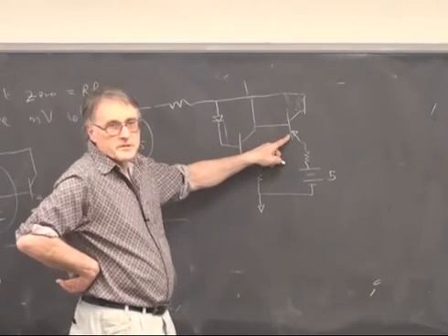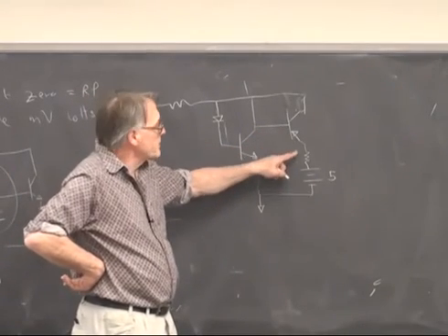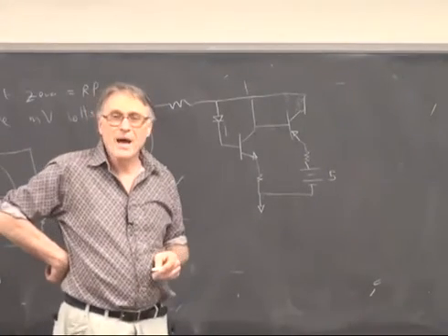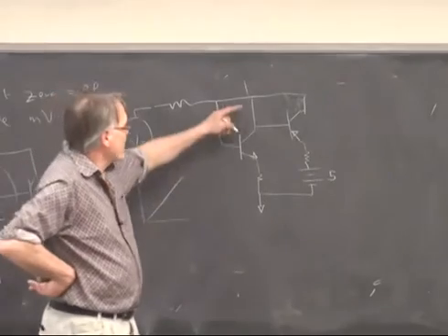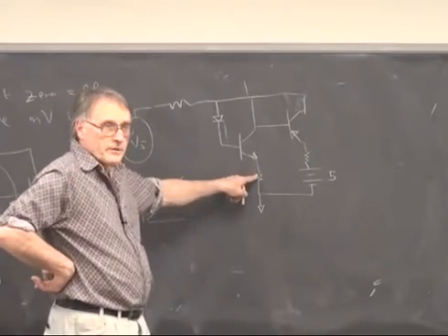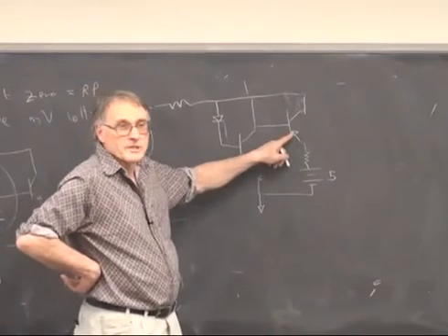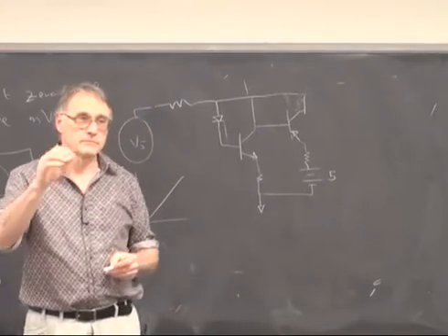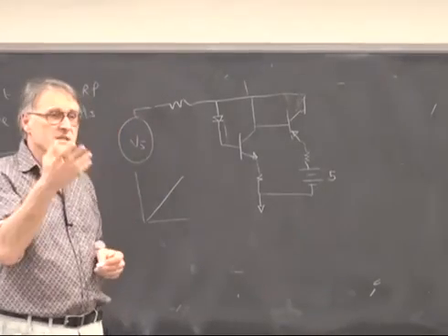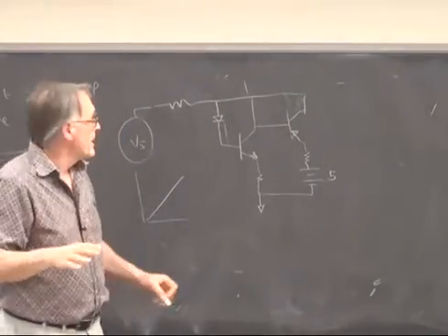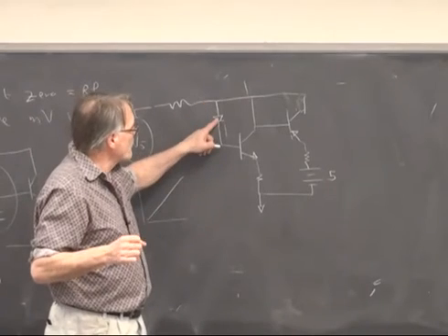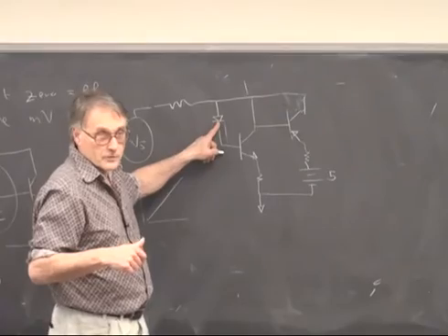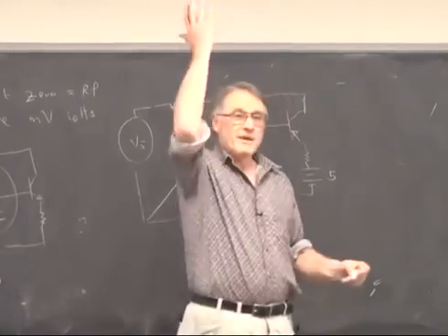That's going to turn on this transistor, which is going to make, interestingly, this point even more positive, drive this transistor further on, which almost instantaneously causes this transistor to go saturated on. So this is the positive feedback mechanism. As soon as you get this voltage going more positive than the diode drop voltage, this circuit slams on and stays on.